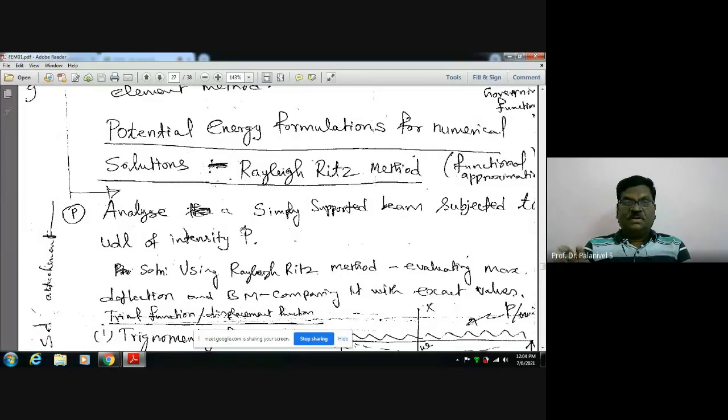Now, external forces are due to loads and internal forces are due to stresses or stress resultants. They are there in the body. So, the total potential energy is the work done by the external loads plus the work done by the internal forces like stresses or stress resultants like bending moment, force, whatever it is. Generally say stresses. This is the total potential energy.